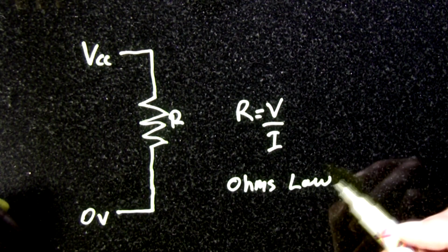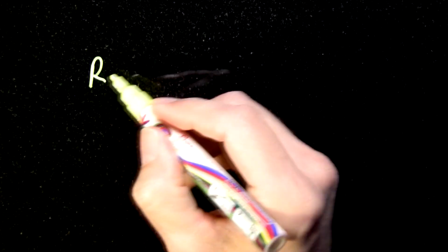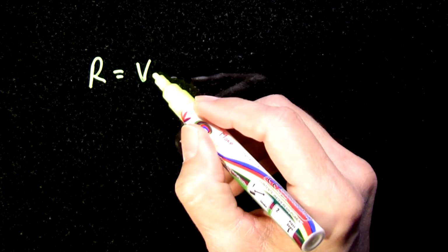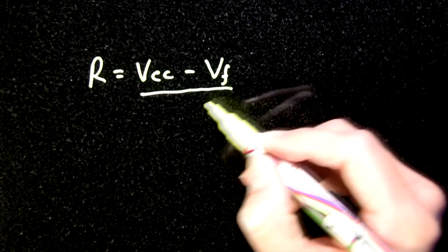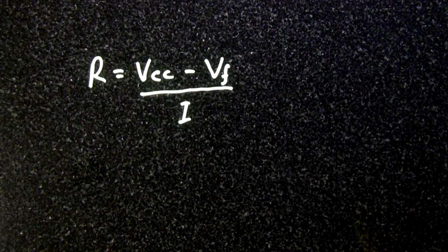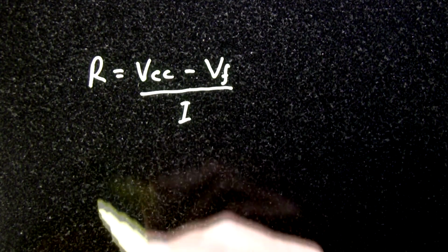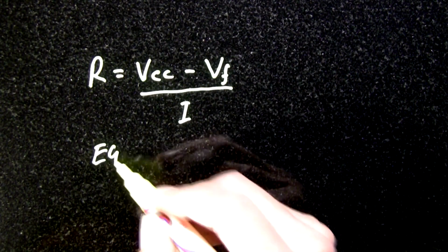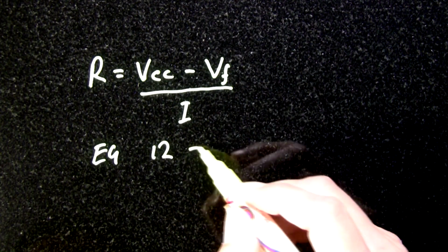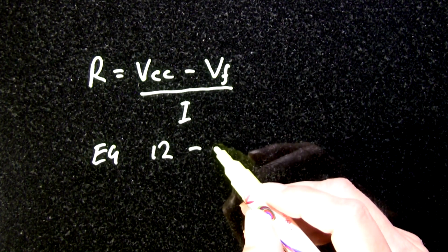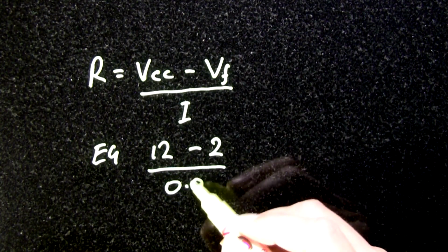What series resistor is needed? Fortunately, the value can easily be calculated like this. All we need to know is our supply voltage, VCC, our LED forward voltage, which we can find from the LED datasheet, and the LED drive current, which we can also find from the datasheet. Once we know those things, we take the supply voltage, subtract the LED forward voltage from it, and then divide that result by the desired LED current.